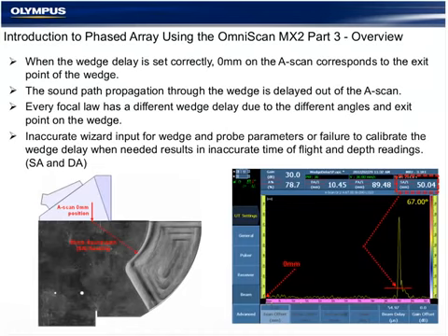If the wedge delay is correct, 0 appears here. If the velocity and wedge delay are correct, then we will also see the correct sound path for a radius or depth for a side drilled hole. This ultimately is what the wedge delay calibration needs to do. So it was initially calculated at 54.97, and going through our wedge delay wizard will make a minor correction to that.